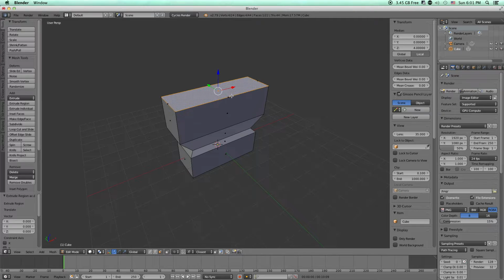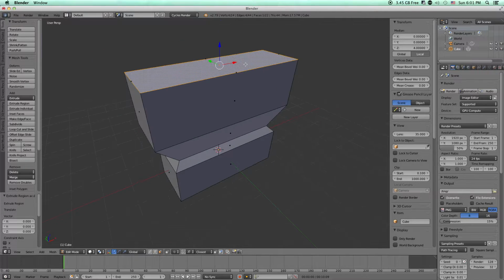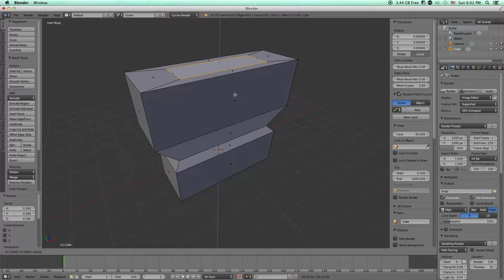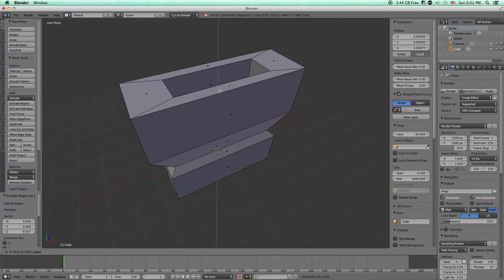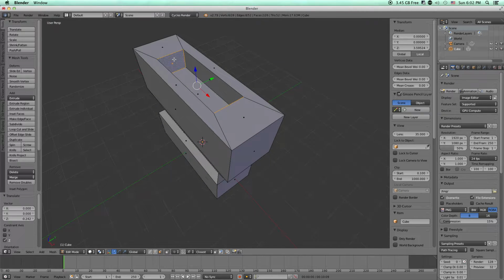And as you can see, there's extra faces in here by those extra dots. So if we scale from right here, go inwards, we can actually extrude again, but towards the inside. And now we have a hole. And you can always edit this hole however you'd like. You can move these however you like.